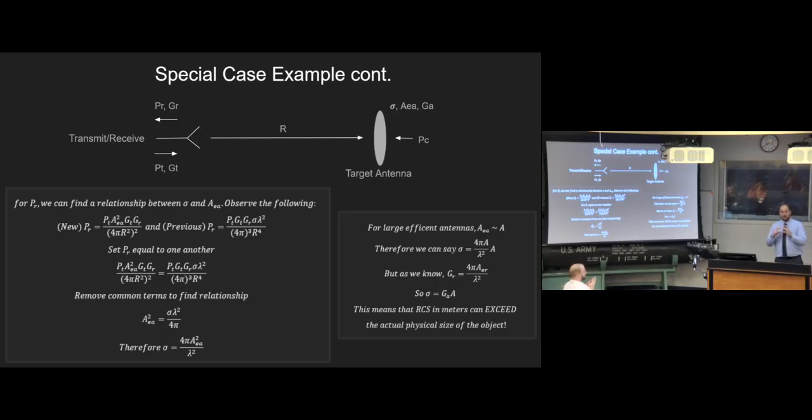Which means that a non-stealth coated surface, it could be a centimeter squared, can light up like a Christmas tree, depending on the frequency that they're using. Most K-band is 24 gigahertz. If you just plug 3 gigahertz into this equation instead of 300 megahertz, 1 square meter just turned into 1,250 square meters. That's pushing the surface area of a Boeing 737. And that could come from 1 meter of untreated space. Now bring it down, be more realistic, say it's a couple millimeters, but say their radar is at 24 gigahertz. You still look huge.